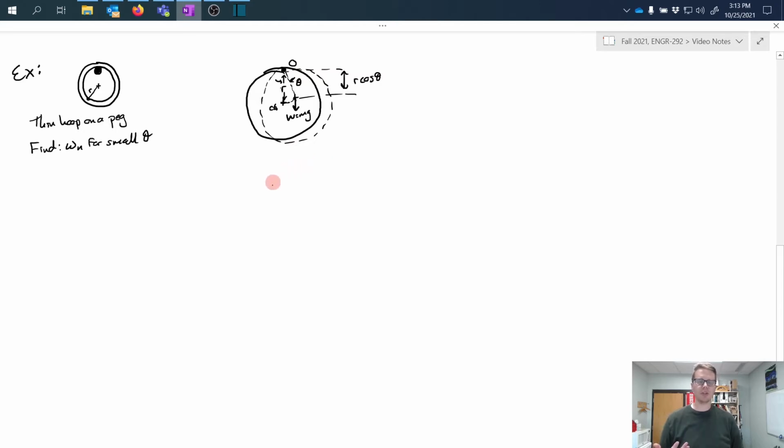So we're going to take a conservation of energy approach to this problem. First, I want to think about what's happening as the hoop rotates around the peg located at O. And therefore, I'm going to represent this as a fixed axis rotation, which uses the moment of inertia about point O times the natural frequency squared. And we're using the natural frequency because we know that if this is being released and is free to rotate, then that rotation must be defined by the natural frequency.